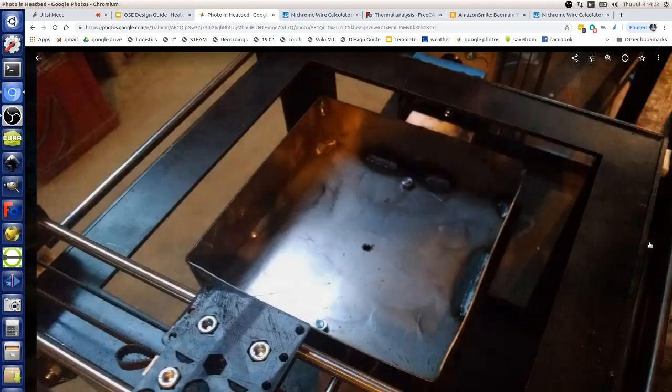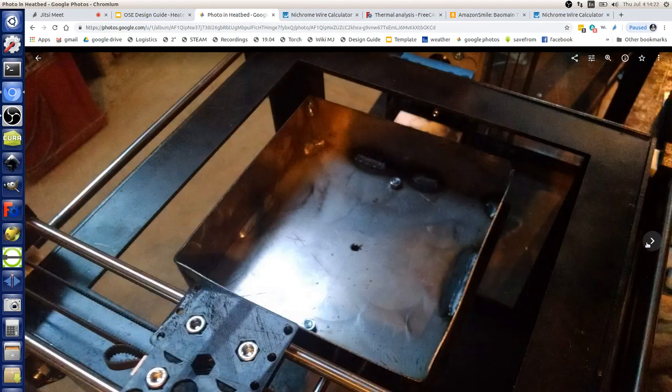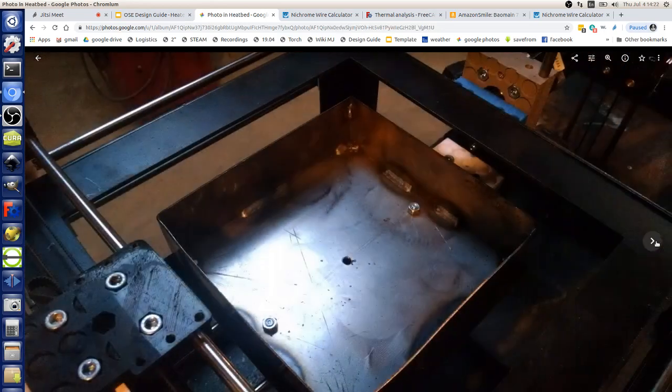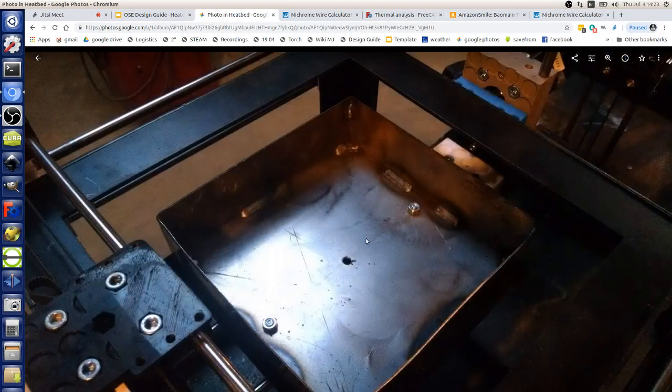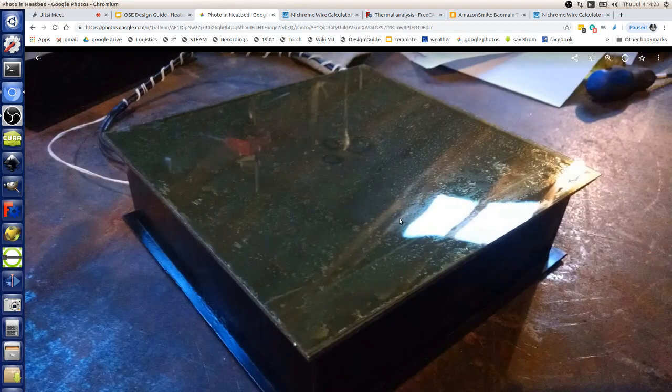That's the heated bed on the bottom. That's a steel surface. We're attaching it through 2 bolts, and I'm using a 3rd bolt to clamp the top surface down. This is the finished beauty. What you see here is a 1/8 inch top plate. It has an elongated metal nut welded to the bottom of that, and we send a bolt through the bed in order to pull this top surface down.